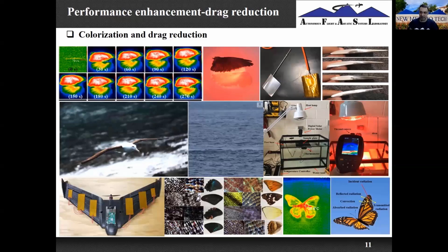So what we did here, we made the wings with different airfoils. An airfoil is the cross section of the wing, which I'm going to talk a lot about during this course. We used heat films at the top of the wing and increased the temperature, and we found out how much this temperature difference would help the lift and the drag in the wind tunnels. So let's look at what would happen in nature, and actually on the albatrosses.